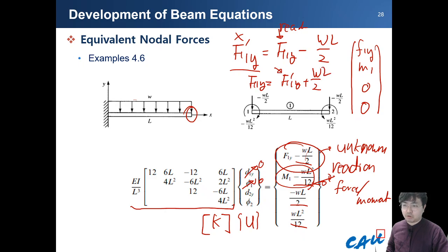This value is unknown the first time it is calculated, but after obtaining the displacement solution, you can multiply. After the multiplication between the local stiffness equations, or sometimes the global stiffness matrices, and the displacement vector, you can finally get the real reaction forces.